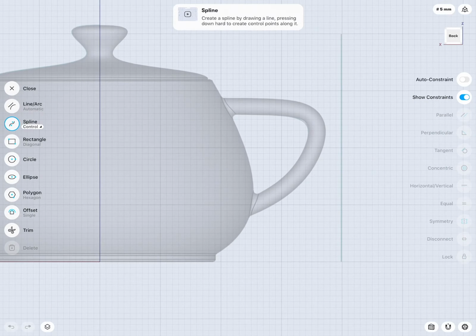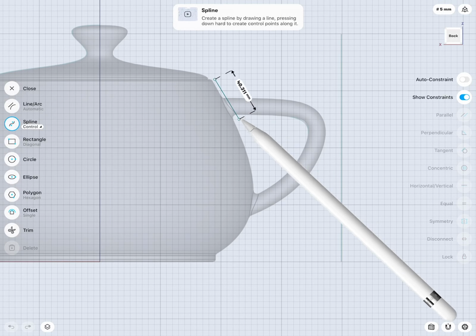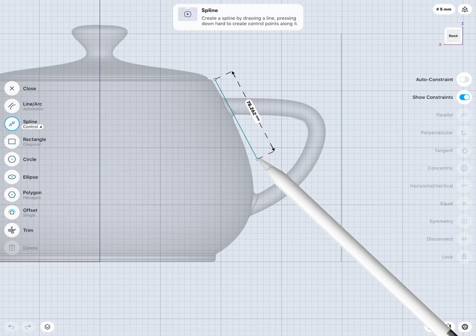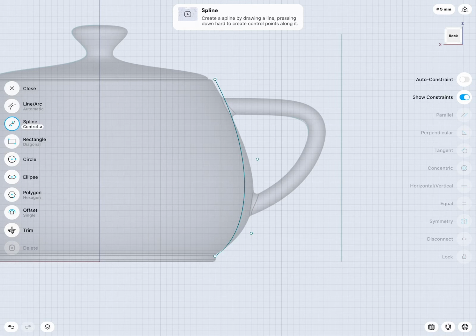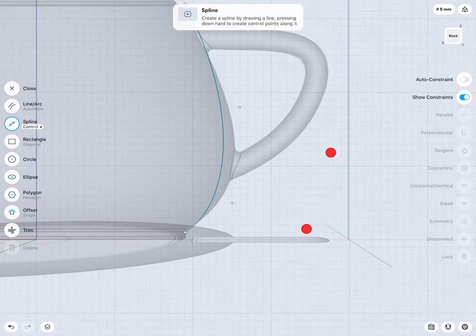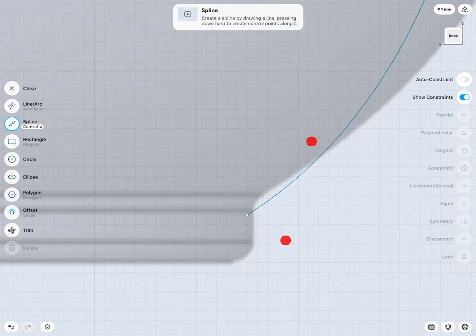Okay, so let's go to sketch, and we would like, as spline, to have the control point curve activated. I start somewhere there, and then start drawing, click, and click, or press on the screen, and here I release. So all we need is a spline with 4 points. The more points you have, the more detail you can put in, but also the more complicated it will be to make a really nice and smooth curve. The least amount of points is always ideal because it makes the work easier and it guarantees better results.